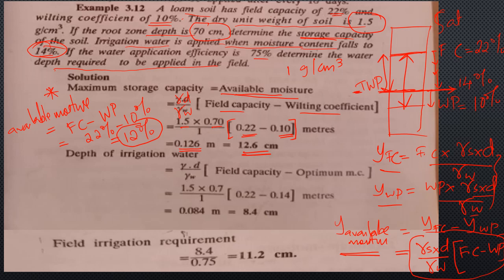This gap is the water available per irrigation, so that the water content is increased from temporary wilting point to field capacity, and this difference, field capacity minus temporary wilting point, is equal to readily available moisture.